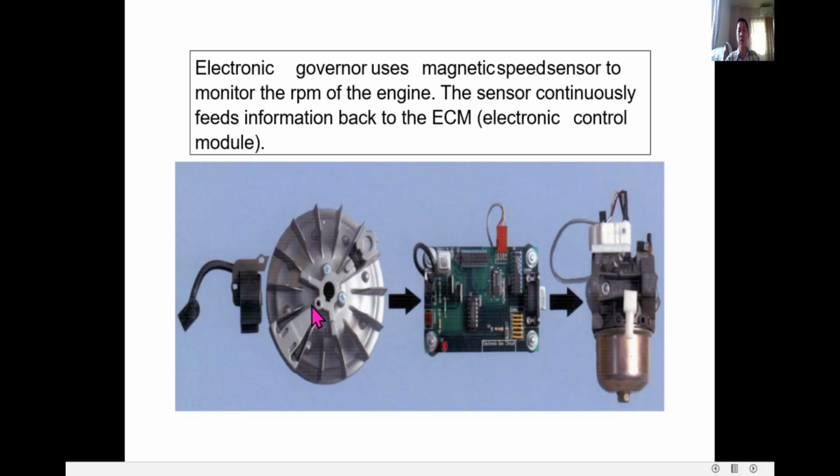This gives what we call the air supply. Actually, this is a combination of an EP converter, electronic pneumatic converter. The electronic signal is converted into pressure of the air, control air.